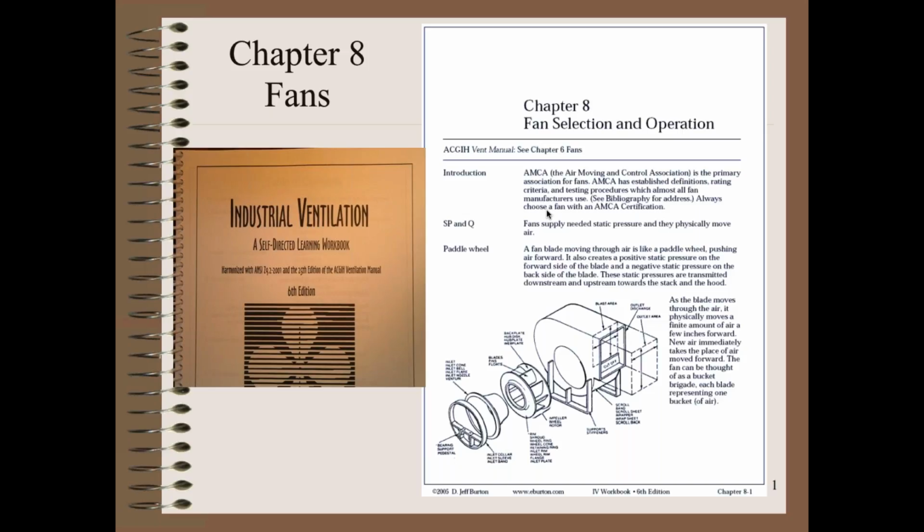But the only problem is that very often you can't just discharge from the fan. You need to move it away. If this is on the roof, you might be able to get away with that, right? But more often than not, you have to go out and go up so you're at least a certain amount of height over other things that are going on on that roof. If the discharge smells bad, you need to go up high. If the discharge is volatile, you need to go up high. If there are other structures or windows nearby, you need to be a certain height above them and so on. There are a lot of codes involved with this, right?